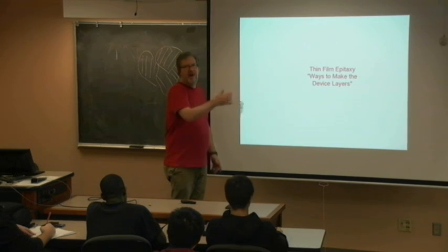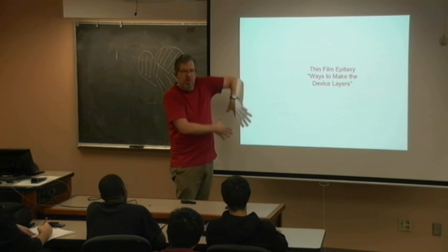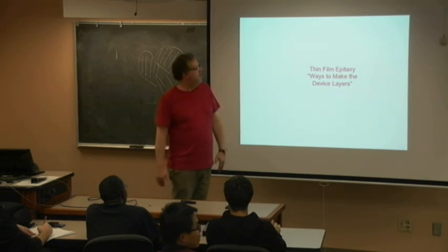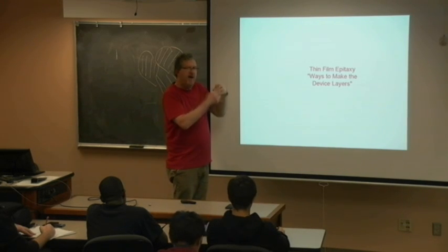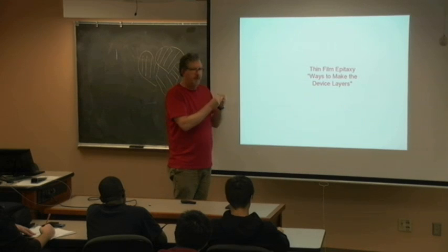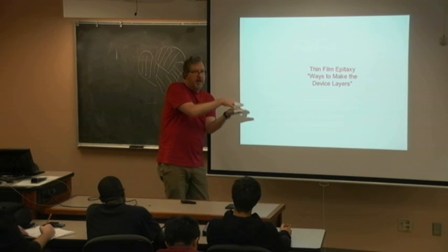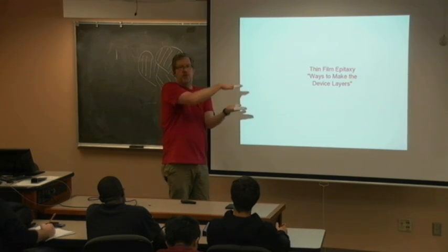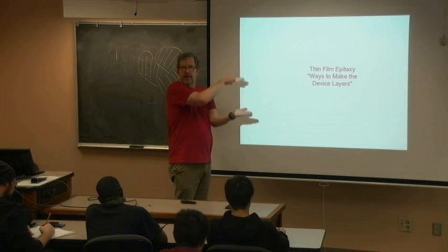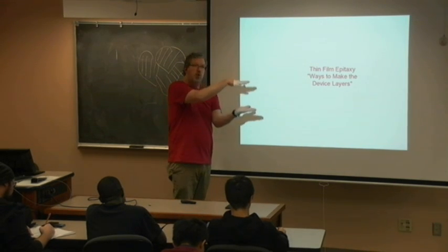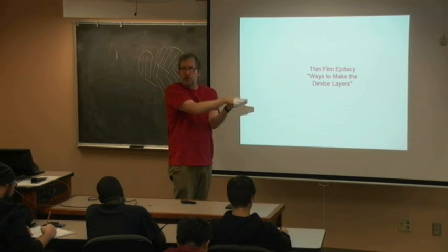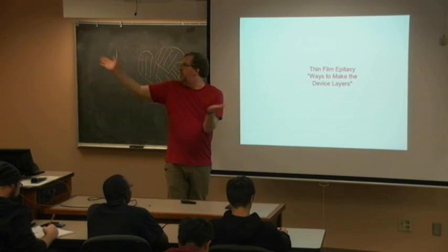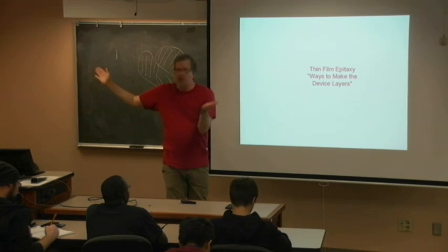Deposition is just putting some atoms on the surface, and they just sort of stick. Epitaxy means they're going to come down and they're going to move around, and they're going to find their happy point, and so they're going to condense. So if I start off with a crystal, it's going to continue to grow in registry with the crystal below it. That was the earlier things, the misfit dislocations and all that. If I cooled it down to a low temperature, I'd just be depositing amorphous goo, right? It'd be a Wagner power painter. It'd be spray painting these sick colored walls here.